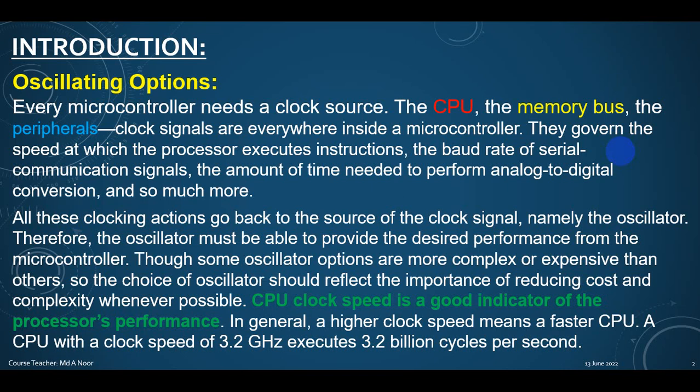The capacitor will get discharged over the inductor, and the inductor will store the energy. After the inductor has fully stored the energy, it will release the energy again, and the capacitor will get charged again. Charge and discharge will create a sinusoidal oscillating signal. We have done sinusoidal oscillating signals in the AC lab.